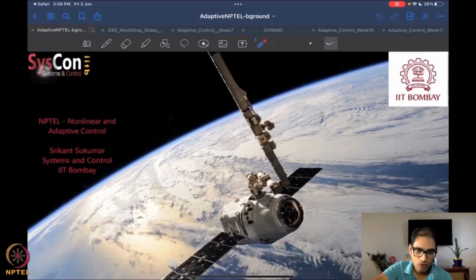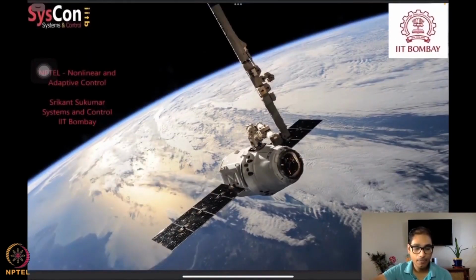Excellent. So what did we look at today? We looked at what happens when you do adaptive control on a very simple scalar system, and then a disturbance is introduced into the system that we cannot account for. Then we saw what happens to the adaptive performance. We almost stared in disbelief and found that you can have unboundedness of the parameters, and therefore unboundedness of the controller, and the whole system can get ruined. So implementing an adaptive controller without some kind of robustness to disturbance can be fatal.